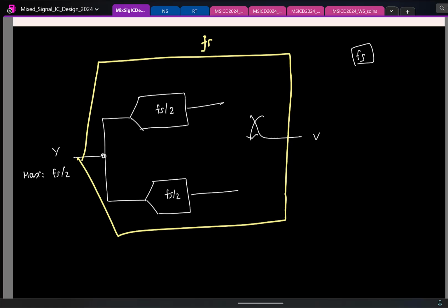That's correct, right? But the question is, if I look at the same scenario in frequency domain, individually there is aliasing, but finally there is none. We are sampling at different times, with a time delay, and because of the phase shift. Yeah, that's exactly it. Anytime the simplest explanation is the right explanation, like Sherlock Holmes says. So here there is aliasing, here there is not. Something must be happening when I combine this, and it indeed gets cancelled, as he's pointing out. So for that, let's actually look at this.